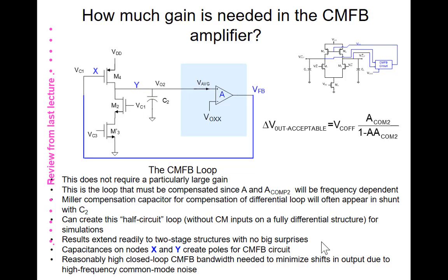So here was the overall structure that we have. I'm just showing it in single-ended form. The other half will be over here. And I don't show the averager here. So this is the average value of Vout1 and Vout2 that goes into this difference amplifier. The averagers are usually very simple, often two resistors.